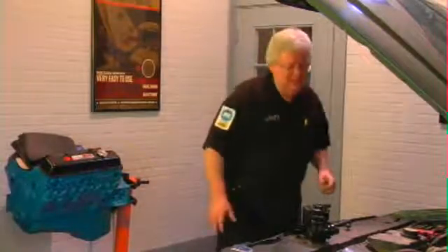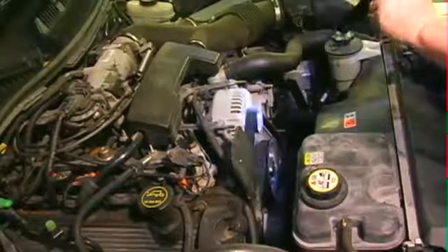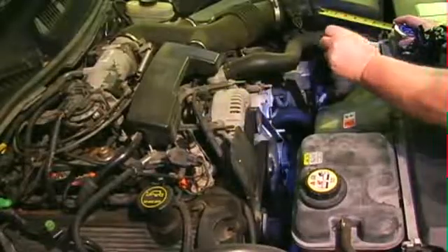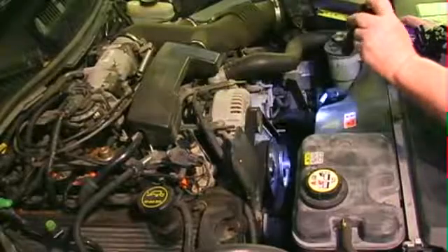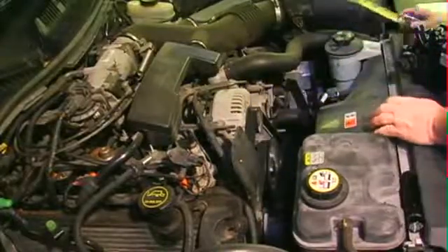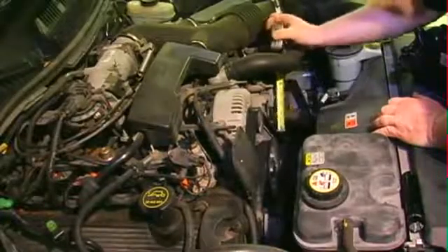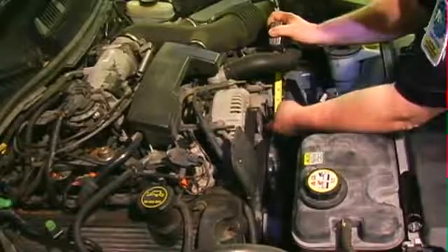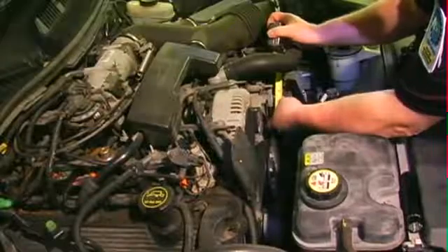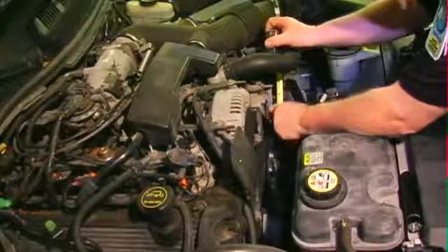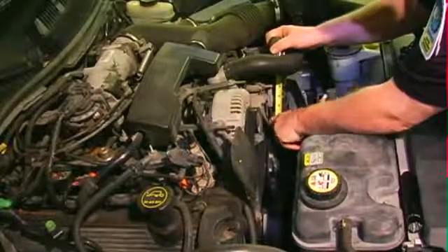To see how much this belt really deflects, I'm going to find the longest stretch. That'd be between the alternator here and the power steering pulley itself. So that's a pretty long stretch. Let's go ahead and do the bending right there. I'll put a tape measure right in front of the camera over here, and I will move the belt up and down. I'm able to get about 1/2 to 3/4 of an inch, and the same thing going downward. If I start at about 2 inches here, I can go down about 1/2 or more.